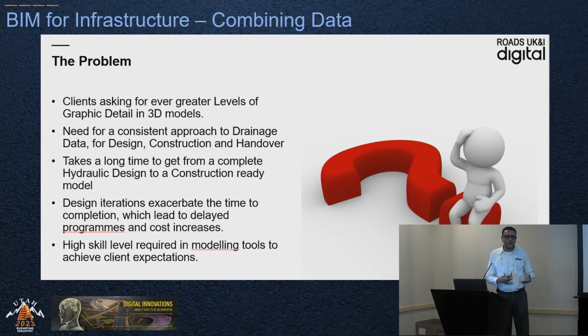I'm going to show an example of a project that I'm working on now that's an as-built of the project, but one of the things we utilized the model for was computational fluid dynamics. Do any of you use that in your organizations, or focus on that as part of your requirements or deliveries for validation of a design? It's important because this is a drainage system for a very large highway segment. With CFD, we were able to find out where we were going to get a geyser effect with too much water.